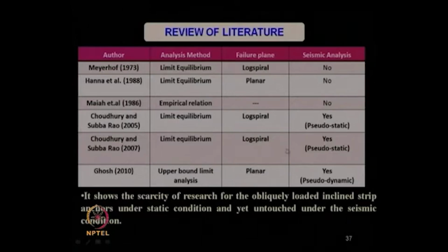Coming to some more researchers' results in this area of obliquely loaded and inclined strip anchors. For inclined strip anchors, Meyerhof in 1973 used the limit equilibrium method, as I said, with a log spiral failure mechanism, no seismic analysis. Hanna et al. in 1988 also used the limit equilibrium method using a planar failure surface, with no seismic analysis.